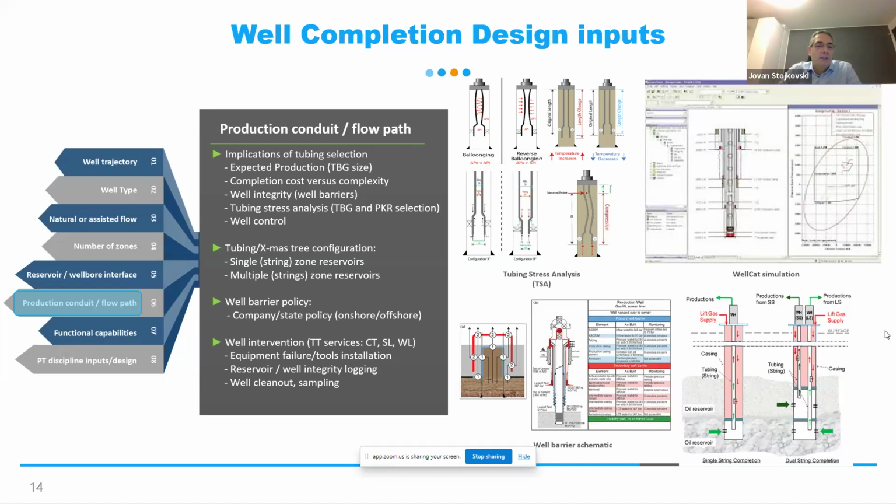But as you know, the tubing we can order can have different metallurgy. It can be like L80 or J55 grade, but metallurgy can also be chrome tubing if we have CO2, or even super duplex material. So these materials will dictate the cost.